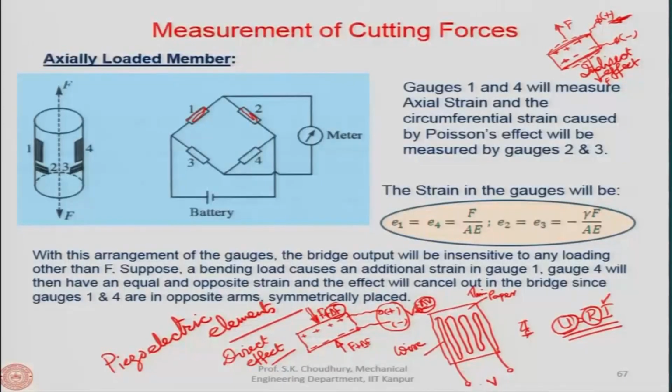That is why it is called ultrasonic machining. Ultrasonic machining is with the help of a very high frequency vibration, and that high frequency cannot be produced with the help of an electromagnet. By high frequency, we mean about 20-25 kilohertz. So, 20-25 thousand times per second, it is the vibration.